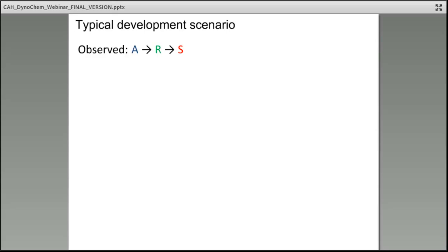We know that addition times will have an effect. We know hold times will. So straight away, when we scale up, we're likely to see more variation. And one thing we want to do, to the best of our ability at the small scale, is be able to predict how our input parameters will affect the output, and what variation are we allowed, and what will let us operate our process within specification and what will not.